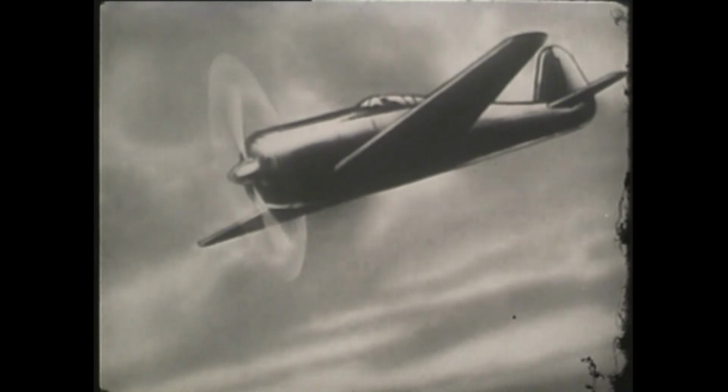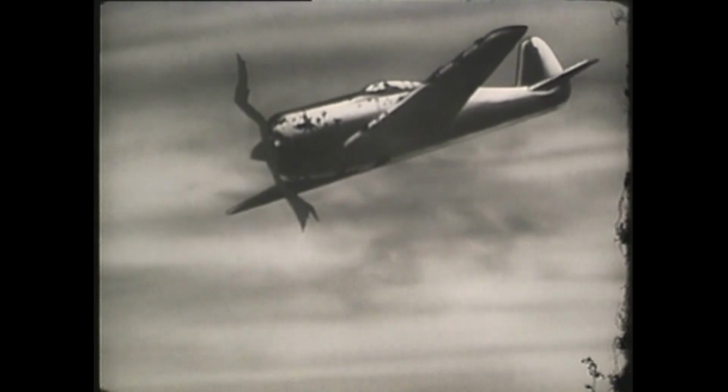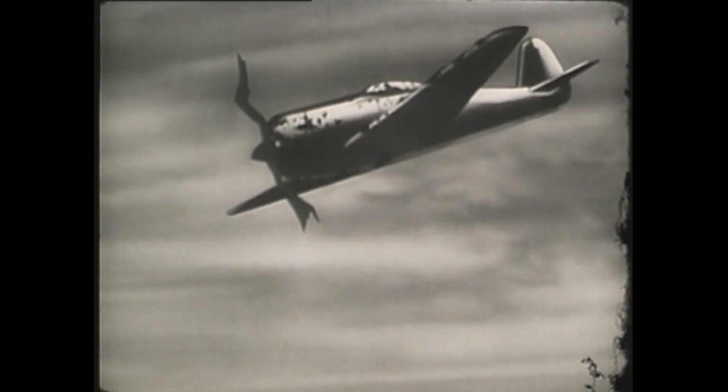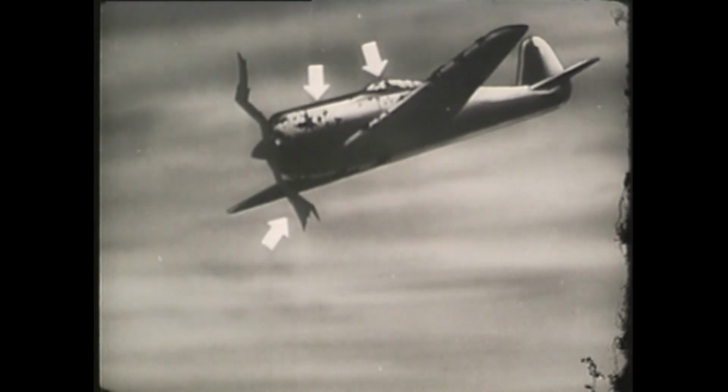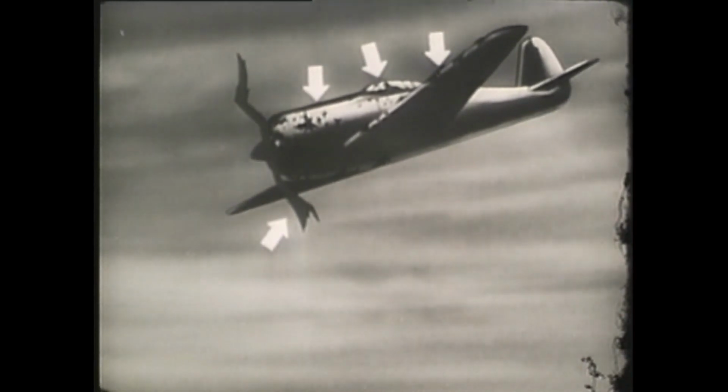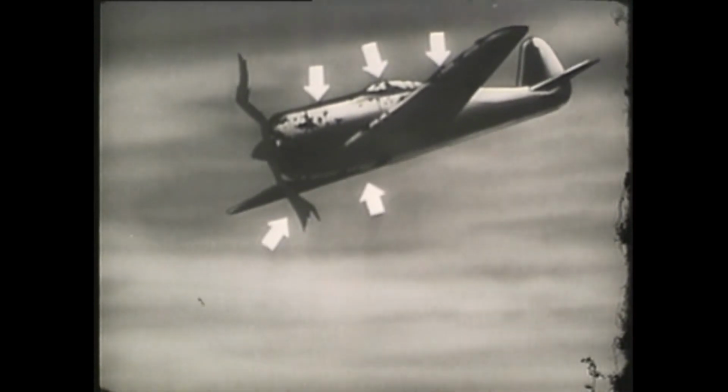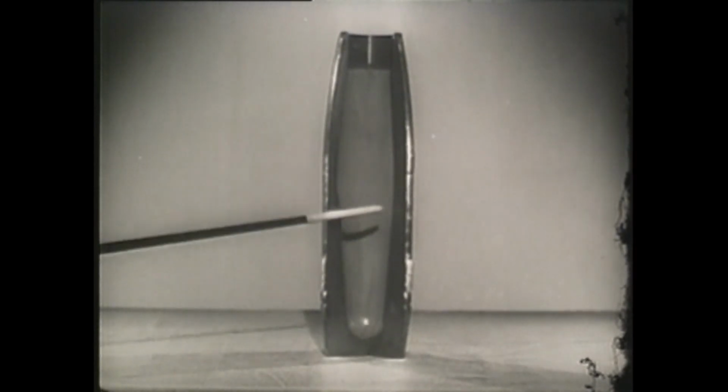Now let's consider a typical application of these fundamentals of terminal ballistics in dealing with an enemy plane. Fragmentation is the effect we want. Besides endangering personnel in the plane, flying fragments can wreck the engines, weaken structural members, and may penetrate the fuel tanks, generating enough heat to start a fire. The shell to do this particular job must carry enough high explosive to shatter the shell case and produce high-velocity fragments of the most effective size.